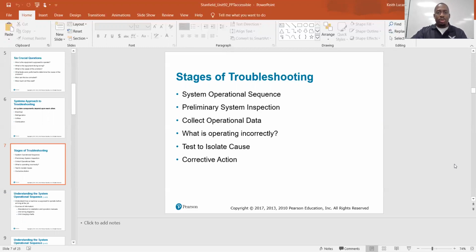You always want to start at square one, which is the thermostat. Always turn it on from the thermostat, see what the system does, and let it go through the sequence of operations. Knowing the sequence will help you pinpoint what the issue is, because once the issue rears its head at that particular point in the sequence, you can rule out everything before it because all that stuff worked. And the stuff after it, you can check later because we haven't even got to it, because we stopped at whatever point we stopped at. So that kind of helps you by knowing the operational sequence.